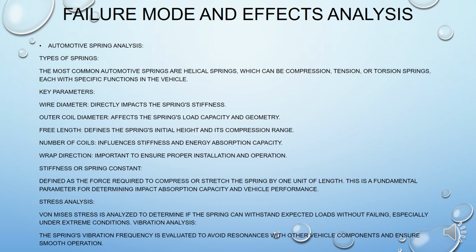Stress analysis. Material strength is analyzed to determine if the spring can withstand expected loads without failing, especially under extreme conditions. Vibration analysis. The spring vibration frequency is evaluated to avoid resonance with other vehicle components and ensure smooth operation.